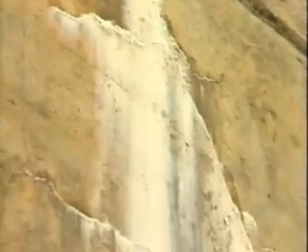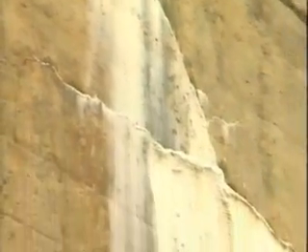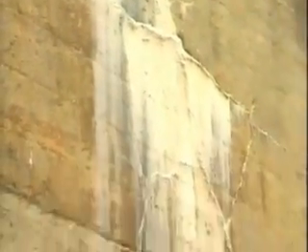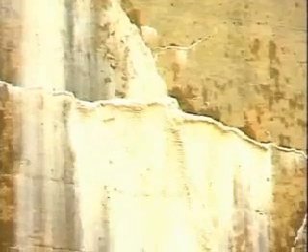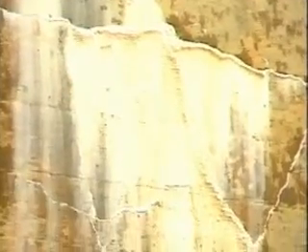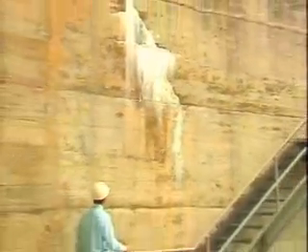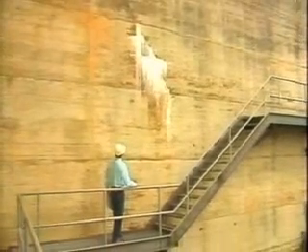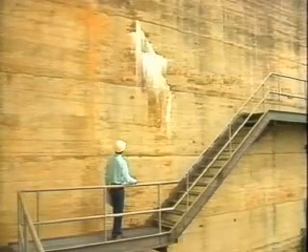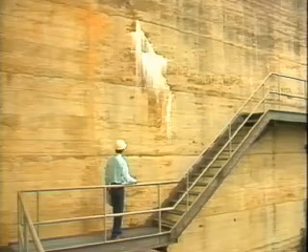Another condition to look for is efflorescence. Efflorescence is the formation of calcium deposits on the surface of the concrete as leakage evaporates. Efflorescence may cause cracks or joints to widen, leading to faster deterioration and increased leakage. However, in some cases, the deposits may seal the crack against additional leakage. Monitor efflorescence and document its progress.